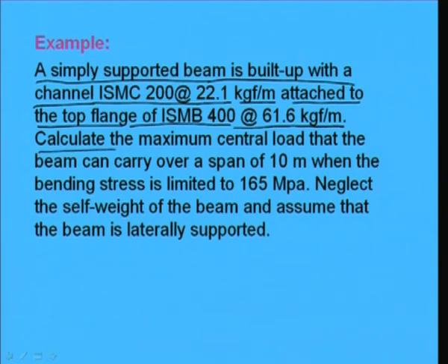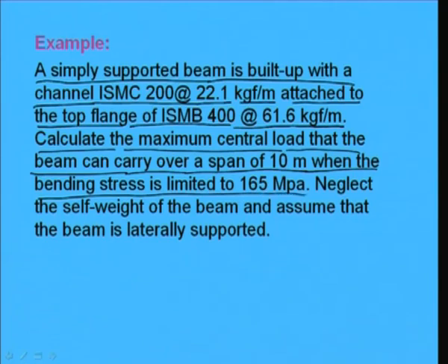Calculate the maximum central load that the beam can carry over a span of 10 meters when the bending stress is limited to 165 MPa. Neglect the self weight of the beam and assume that the beam is laterally supported.